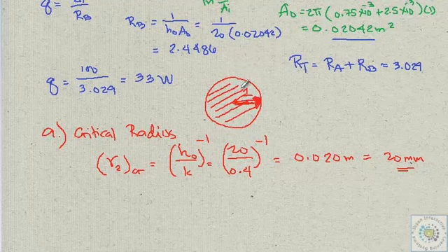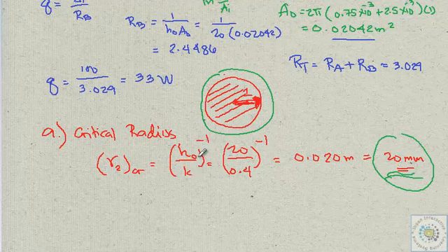Your pipe is already quite big, and putting insulation on that material will not increase the heat transfer but will prevent heat from flowing out, because you are already far beyond the critical radius. So as you can see, the critical radius is normally only this big, 20 mm, because h_o depends on the air, normally at 20, and the conductivity will not go beyond that. So that's it.